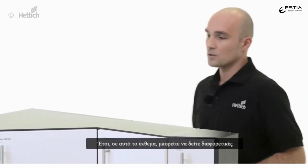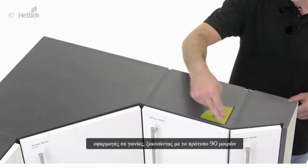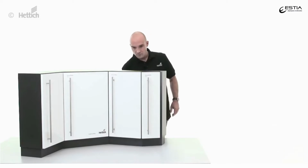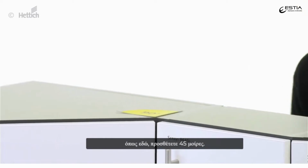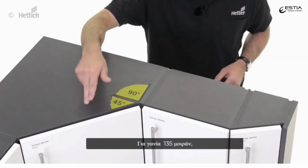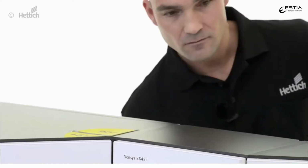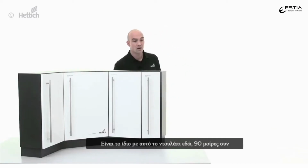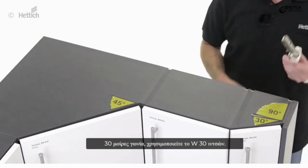So on this exhibit, you can see different angle applications, starting with the standard 90-degree angle and with the standard hinge. When the angle is over 90 degrees, like here, you add 45 degrees. For a corner angle of 135 degrees, you use the W45 hinge. It's the same with this cabinet here, 90 degrees plus 30 degrees angle, you use the W30 hinge.